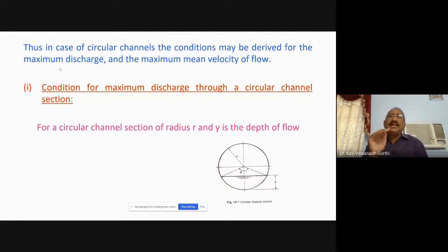So based on that parabolic or logarithmic velocity distribution, depending on the flow being laminar or turbulent, we have assessed the average velocity at a given section. That is what is also called mean velocity. So we have mean velocity, we have the local velocity or the velocity at a given point, and the maximum velocity. There are three different things in the case of pipe flows.